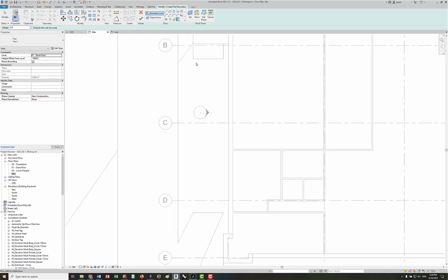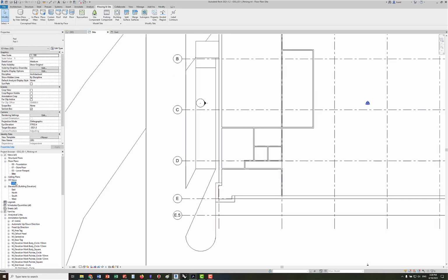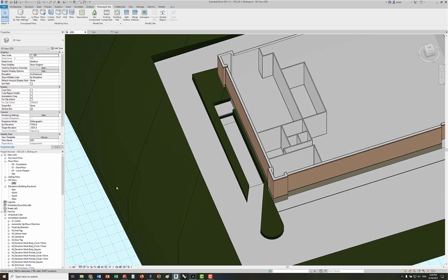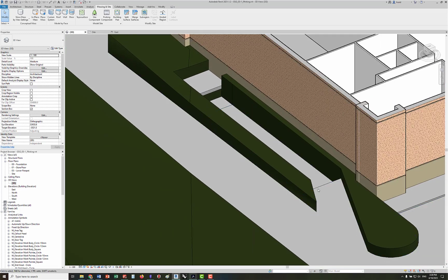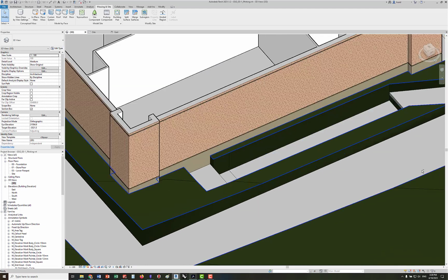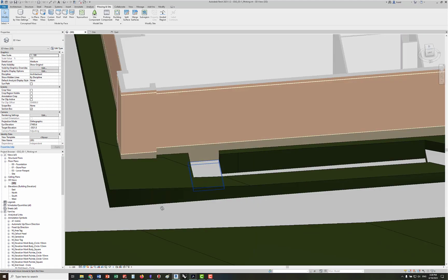So going to the site, I will draw a new building pad representing this asphalt driveway or ramp, and I will draw basically this rectangle from here to here. Now, if I keep it negative 1065, it's going to be the same elevation as this one. So let's see how this will look. So it's the same elevation as this one, if you can see it. But then there's this big drop here on this side. So it's not a ramp.